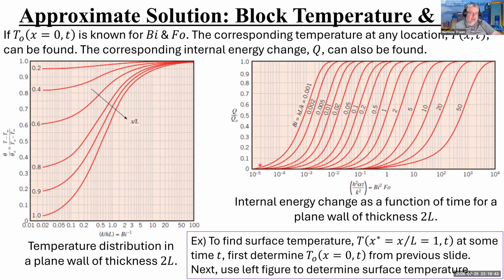And again, bounded by 0 and 1. Why? Because we've non-dimensionalized this. The maximum amount of heat that could possibly be absorbed is if we let this thing go to basically infinite time, right? So infinite time is way up here at the top, where Fourier number gets just really big. You can see these go off asymptotically to infinity, but right before infinity, they're those values for 1. And if you give very little time, Fourier number is very little or 0, then all these guys collapse to 0, and you absorb no heat, because you haven't given enough time for the heat to convect or conduct into your object, right? Okay, so internally it's all self-consistent.